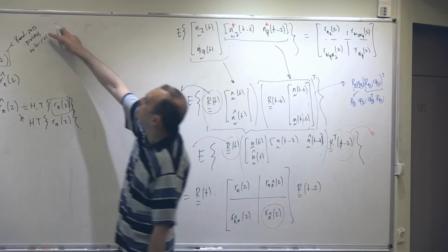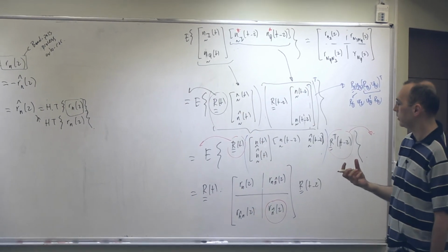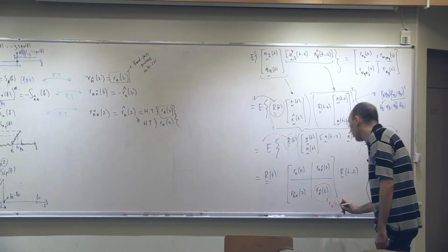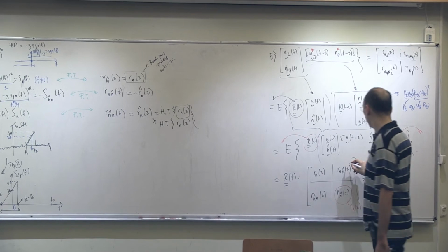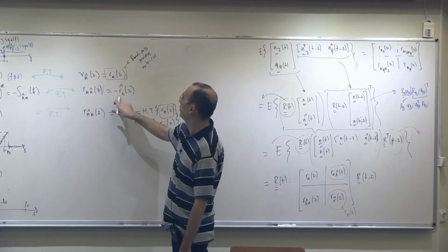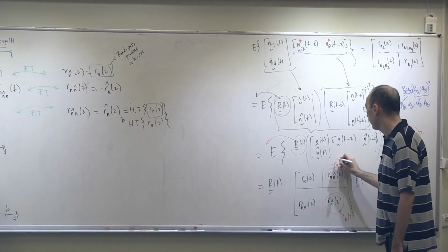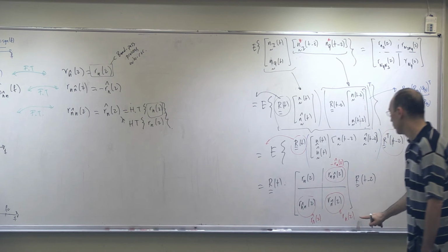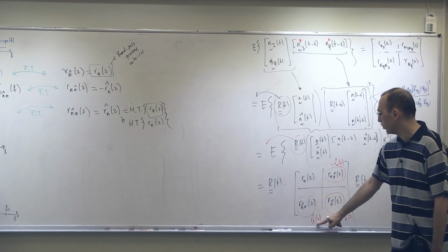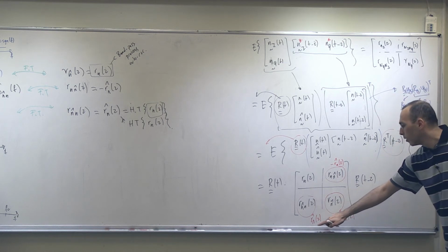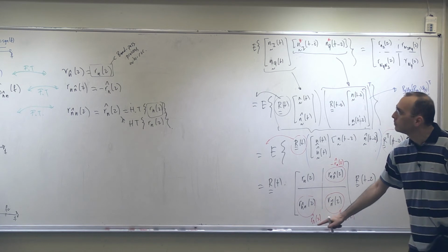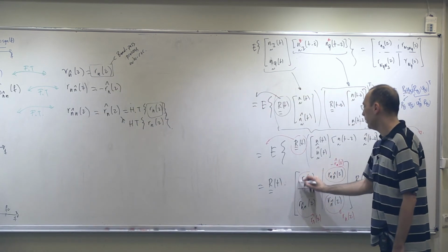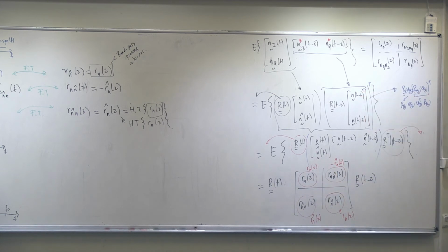Well, of course, I know my bandpass process. I know the bandpass process power spectral density and its autocorrelation. This is my very first input. But I didn't know this. But this turns out to be R_n of tau. Okay, very good. How about this one? This one is this thing. This is the Hilbert transform of that, but with a minus sign. This is the Hilbert transform of the autocorrelation of this bandpass random process. Okay, R_n of tau and n hat, I have over here, and this is this. R_n of tau, no changes for that.